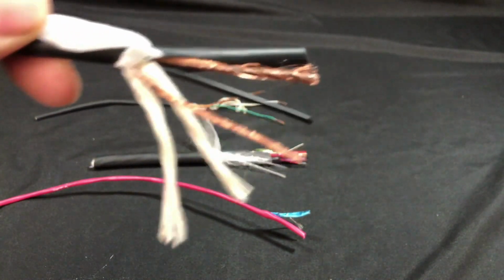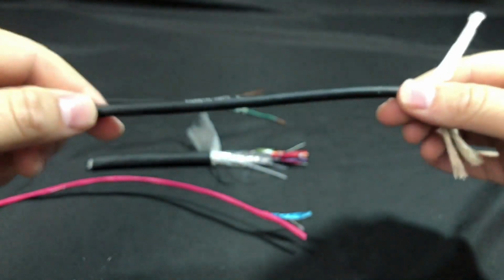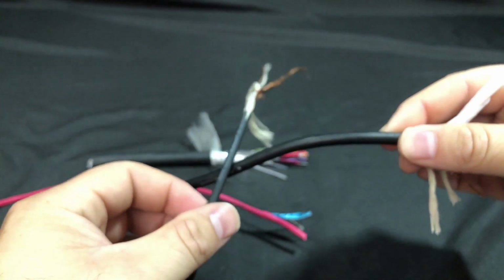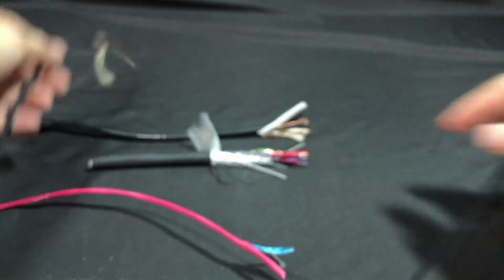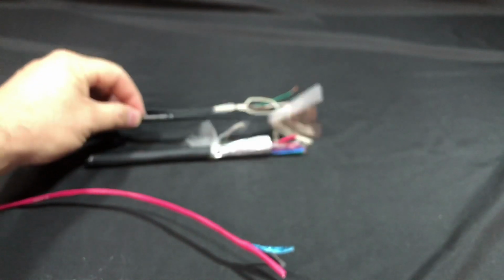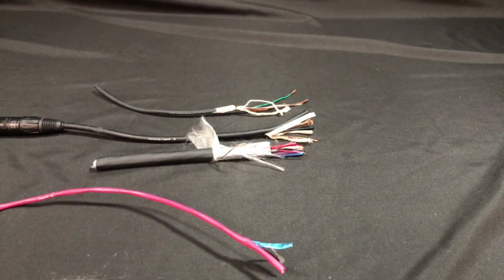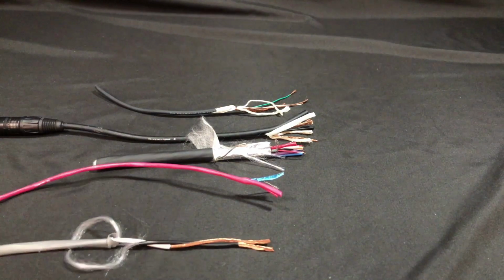However, electromagnetic interference is much more important because if you're running this across the stage, you're going to intersect and come across different cables, maybe holding different power supplies. So like if you're powering a piano or a keyboard or something, that microphone cable or instrument cable is going to come up really close to those power supplies, and you're going to have a lot of electromagnetic interference. So braided shielding is better for that purpose.